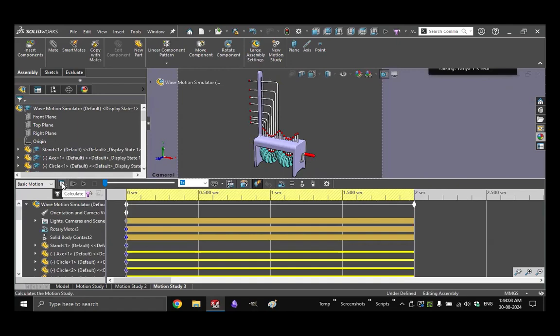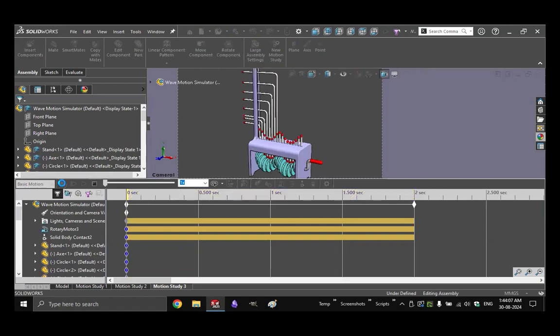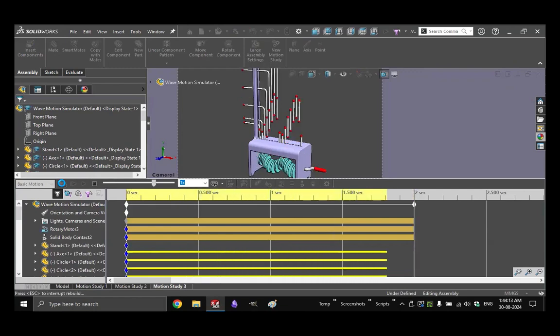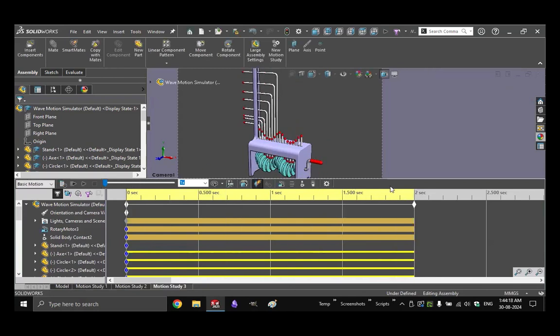So no tangent mates, nothing. Now let's hit calculate once again. This time it should work perfectly. And as you can see, the rods are rotating. But what's happening here? Okay, I should have expected that. Well, technically it's not wrong, because these are actually hitting the rods, and the rods are being pushed upwards, but nothing's actually telling the rods to come back down again.